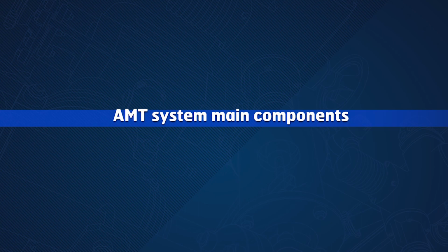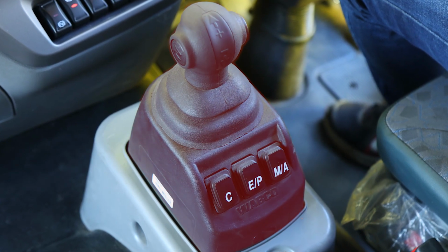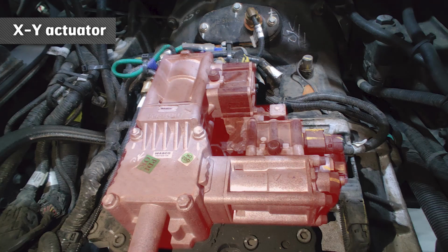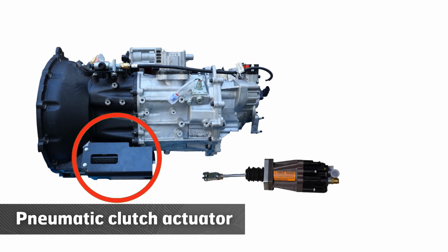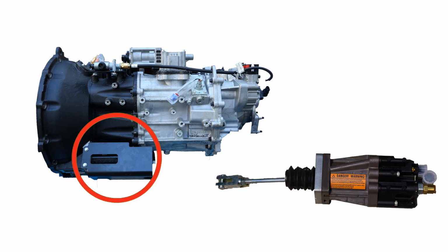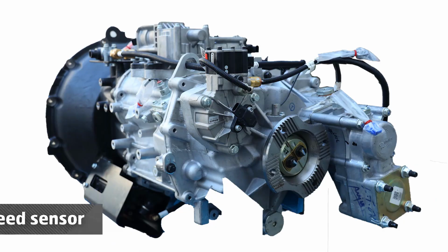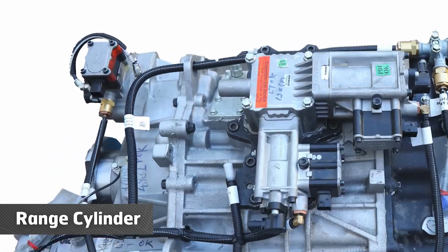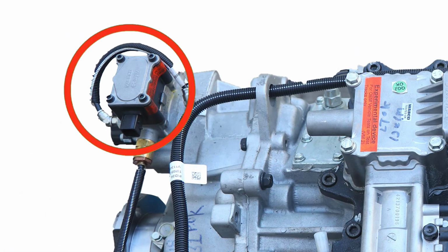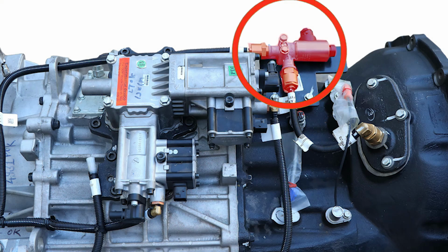AMT system main components: cabin mounted shift lever unit, SLU, including the system's electronic control unit; XY actuator mounted on the transmission to select and shift the appropriate gear; pneumatic clutch actuator to engage and disengage the clutch; input speed sensor mounted on the transmission to calculate input shaft speed; output speed sensor mounted on the transmission to calculate vehicle speed; range cylinder mounted on the transmission, used for range shifting from low to high gear and high to low gear; counter shaft brake valve mounted on the transmission to actuate the counter shaft brake during gear shifting.